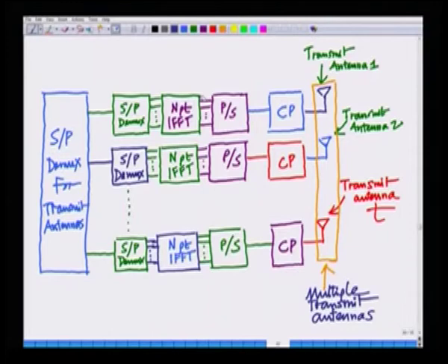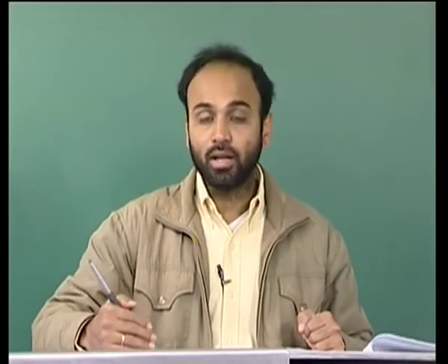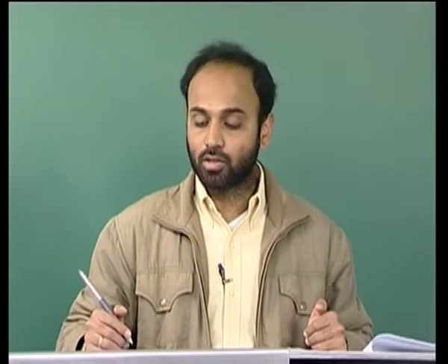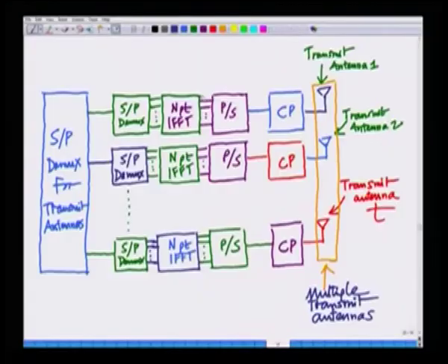Okay. So, this has to be performed at each transmit antenna essentially, and before that I have to take all the available symbols and divide them amongst transmit antennas. So, let us say I consider a system with N equals 256, for instance. Let us say I have an example, N equals 256 subcarriers and T equals 4 transmit antennas.